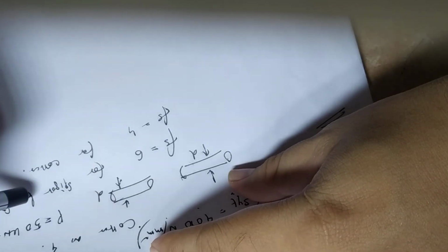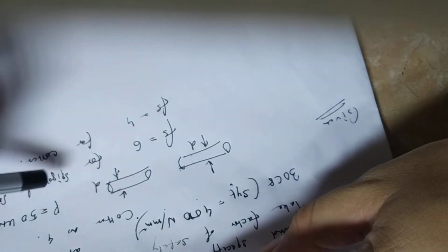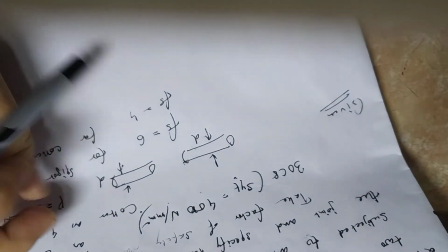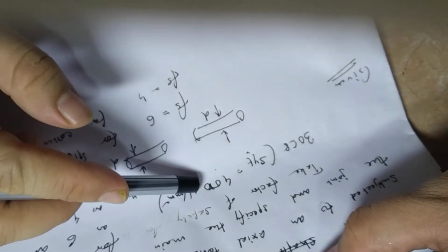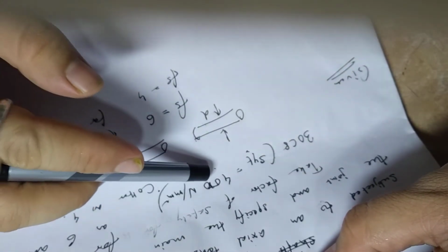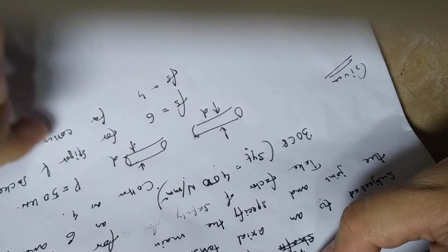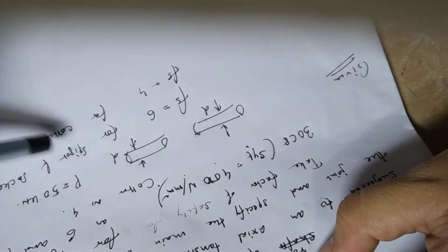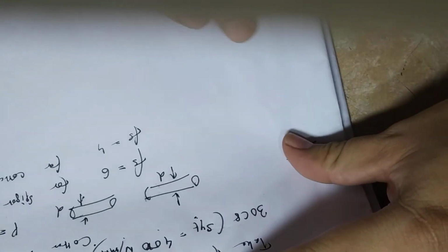So you see, factor of safety is 6 for socket. You have understood, because we have to keep the allowable stress very much below the failure stress. In this case the failure strength is 400 Newton per millimeter square, you can also call it yield strength. We'll keep it much below for both, but for socket and spigot we'll keep it 6 times less, and for Cotter 4 times less than this value. So let's find out the allowable values.